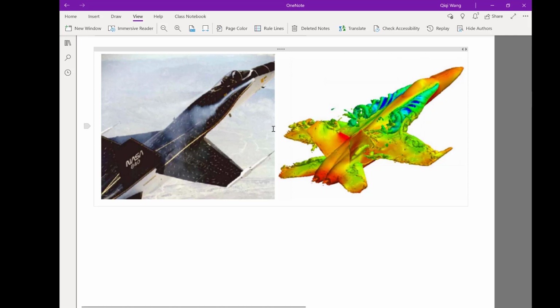So this is an example when people fly, typically twin-tailed airplanes, and they find out the airplane actually shakes a lot, especially at high angle of attack. So there are cases where the airplane shakes so much that the pilot actually can't see clearly what's displayed on the screens. And some of the vertical tails get shaken so much that their replacement cycle is something like 10 times more frequent than advertised. I mean, this is usually something that is found out after the design.